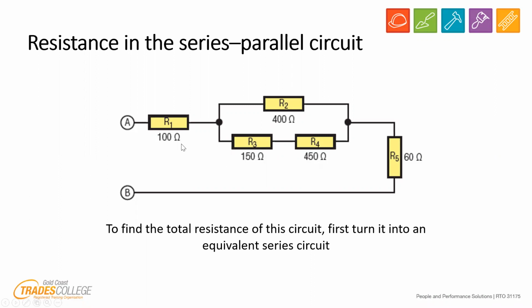Well, the first step, and I'm going to annotate this for you, is to work out how it's best for us to simplify this circuit. If you remember, I'll write the rules up on the left-hand side. For series, the total resistance equals, we add them up, and so on.